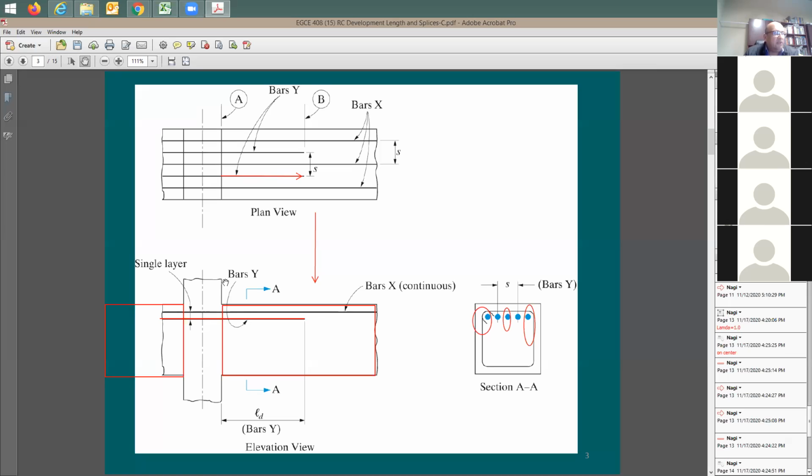Got it. Thank you. It depends on the type of analysis that you do. This makes sense? So let's make it this way: development length is going to be the distance from the point that you don't need the rebar at to where you stop it, where you trim it. All right, you're good? Alexis, you're good? Yes, I'm just writing this down. Very good, excellent.